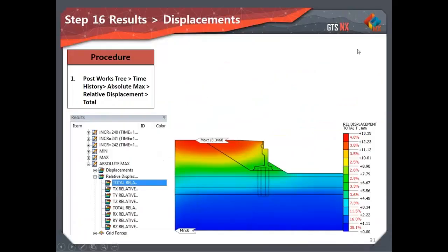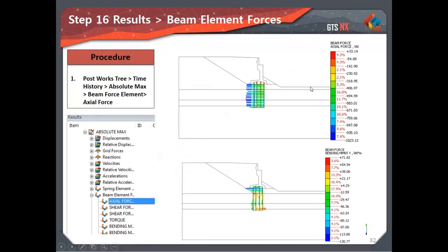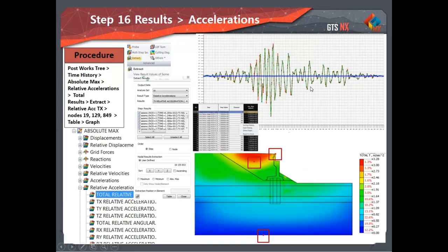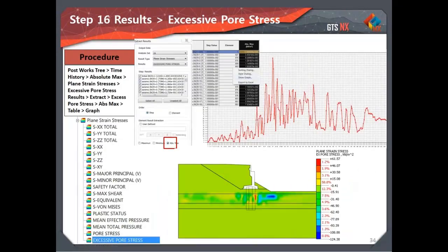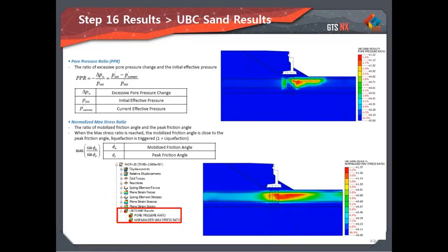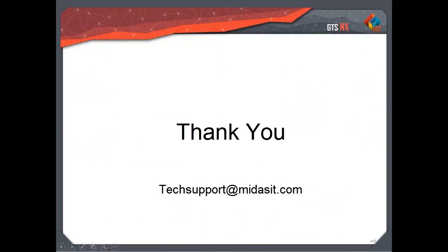So that would be the, I guess, recap of the results. This is a very handy tool, the extract function, for these kinds of seismic analysis where you need to graph what's happening. And these are the special results that we have for this liquefaction analysis. So that would be the conclusion of our step-by-step training.